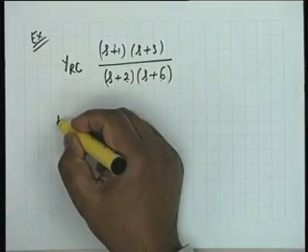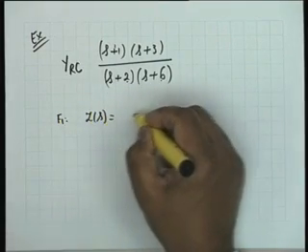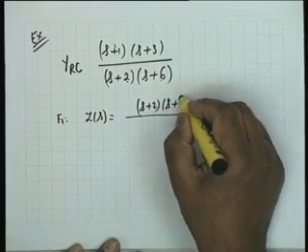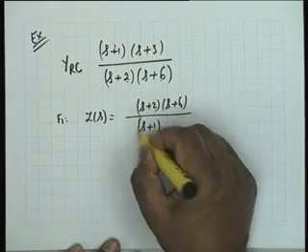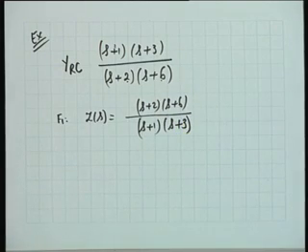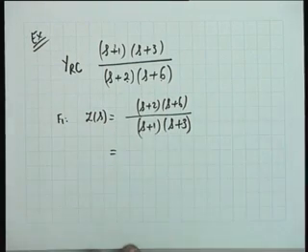And therefore, for Foster 1 you have to take the impedance function Z of S, which is equal to (s plus 2)(s plus 6) over (s plus 1)(s plus 3), and expand in partial fraction. One has to be careful.